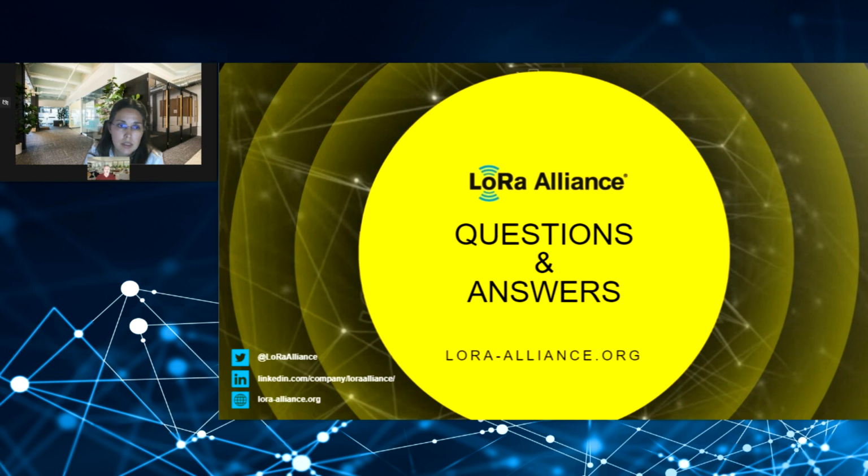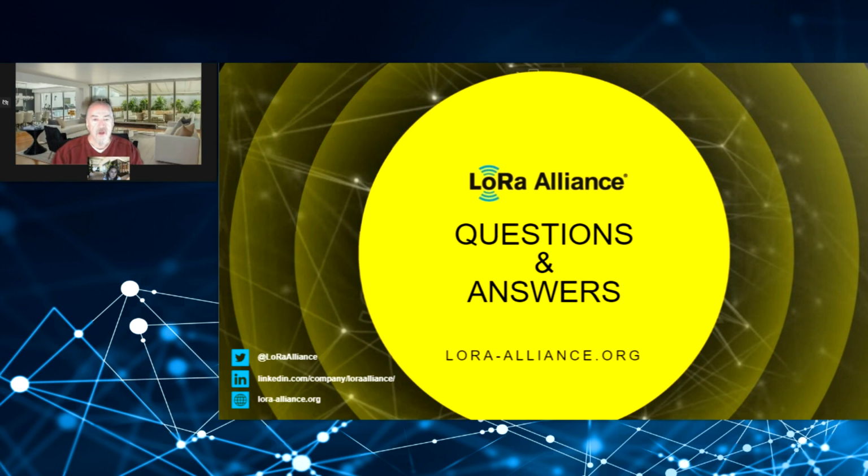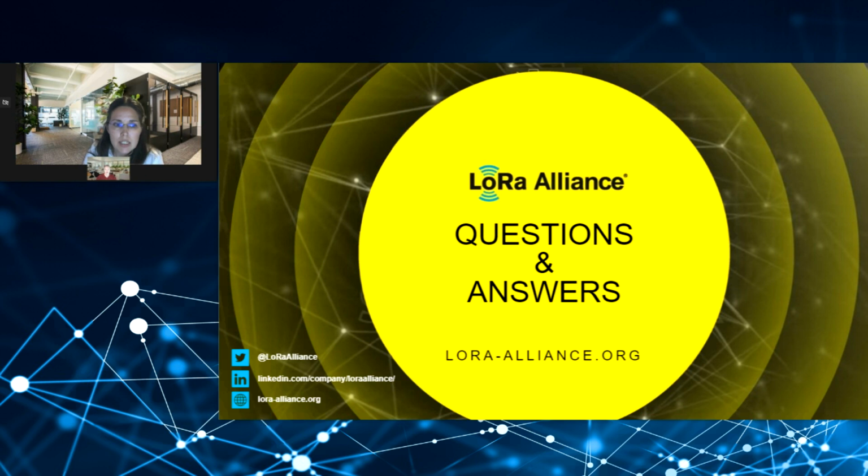Okay, great. Good question. Next one. Does LCTT perform different tests for certification by similarity as compared to a new device? Yeah, they are quite different. If you're running a complete certification for a new device, it's required that the end device has the certification port enabled and the certification protocol implemented. And the LCTT will run all the cases, controlling the device in order to run everything automatically.